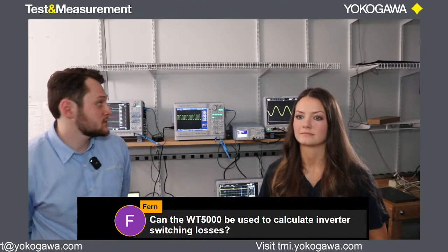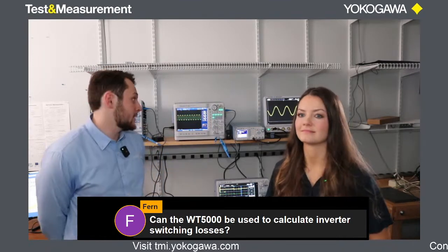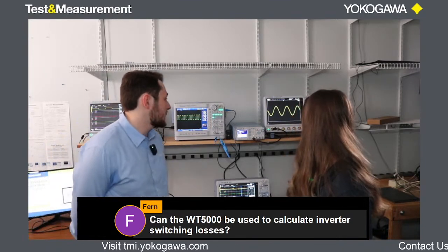We have an oscilloscope with a specific function to analyze these switching losses, and it samples at, what is this one, like 500 megahertz? Which is significantly faster than what the power analyzer is set up to do. So the power analyzer, the WT5000, can't do inverter switching loss, but our oscilloscopes, the DLM3000 and 5000, can.